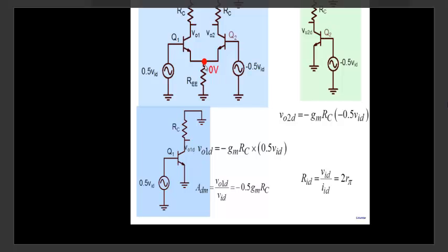in differential mode, you can go ahead and put it. But remember, Q1 and Q2 have to be matched. Q1 and Q2 have to be matched. So all that I'm saying is above this particular point, you could put RC1, you could put RC2, and still, because the collector voltage does not have a big impact on the current flowing through Q1 and Q2, I don't have to bother too much about these parts here. I would still have a reasonable small signal ground here.